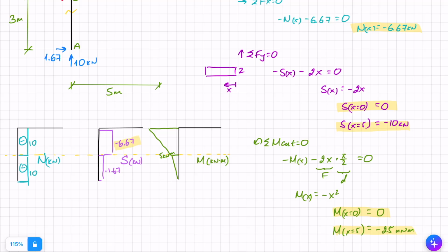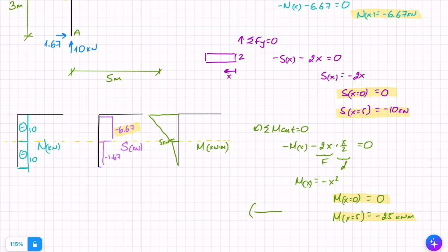My only question is, what side do I draw this on? Here, I assumed that this was the moment. It's not the case. The moment is really in this direction, meaning tension at the top. And that makes absolute sense here. These are the same, right? This was 25 and this is 25. And they're on the same side of the corner, which means that they are, just like we drew before, in equilibrium with each other.